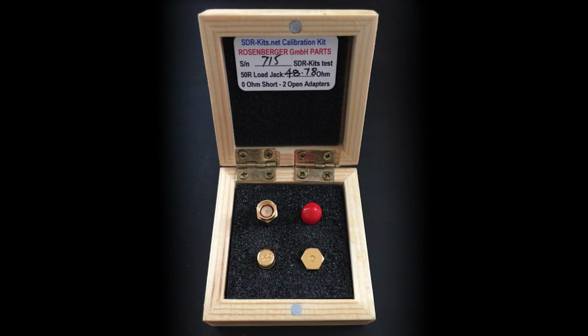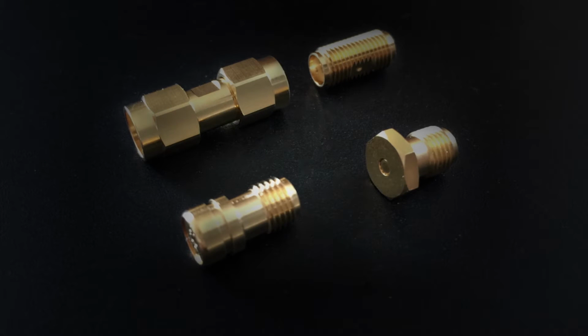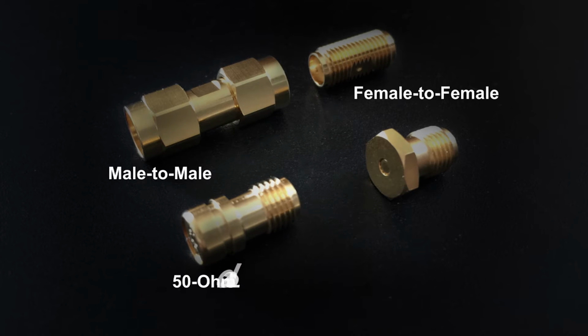Let's return for the moment to the topic of calibrating the Vector Network Analyzer. SDR kits can supply a calibration kit which comes in a small but professional-looking wooden box. These are all SMA connectors, and the next picture shows the 4 pieces in the kit. A male-to-male connector is in the upper left, a female-to-female connector is in the upper right, the 50 ohm load is in the lower left, and the short circuit connector is in the lower right.